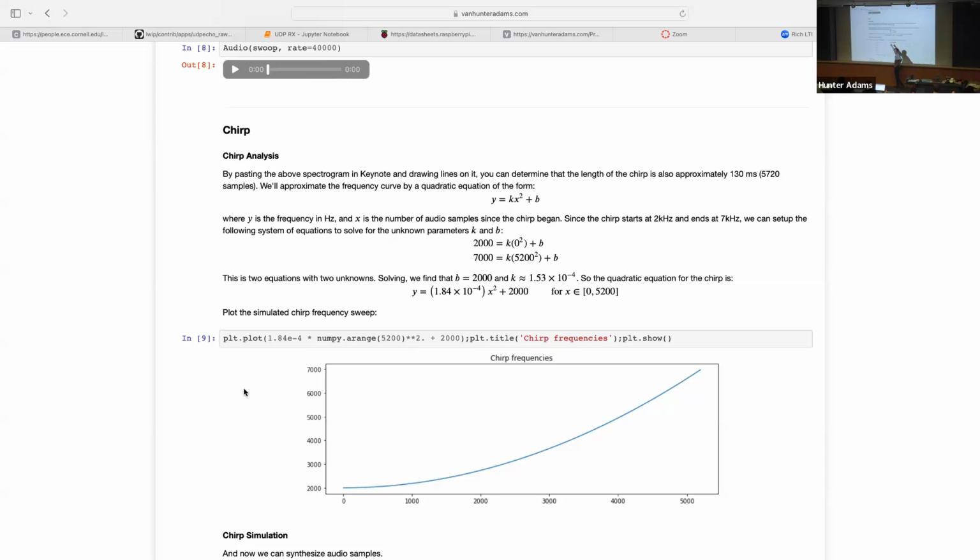But I want to just point to this function. Some of you may have in the past used the inbuilt C function pow to take a number to the power of some value. That is so slow. Like if you use the scope to measure just how long it takes to compute pow, it takes forever. It is so much faster than that to say, I'm just going to take x and multiply it by x. The multiply is faster than the pow. Even faster than that,